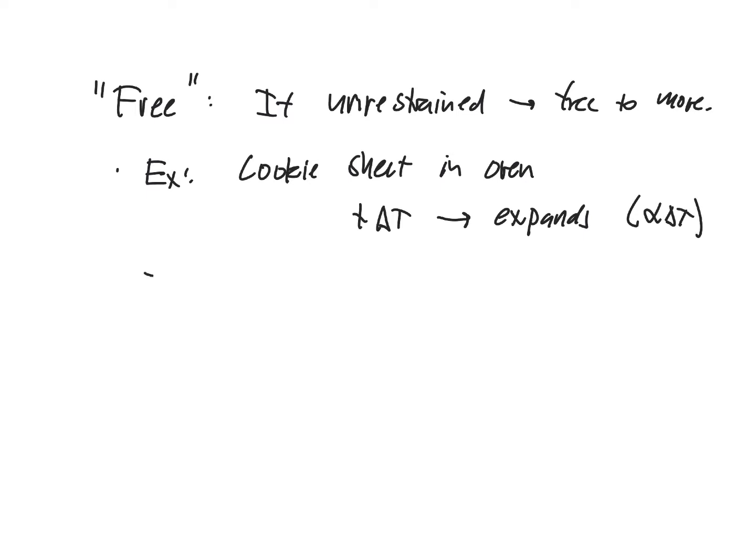But the important thing is if we cut a free body diagram and look at the edges and look at the forces on it, other than the force that's generated by its own gravitational support, then if we make a cut and draw a free body diagram, there is no stress. So it's possible to have strain without stress. This is our first example of that, I should say. It's not the only one. So we can have strain without stress.